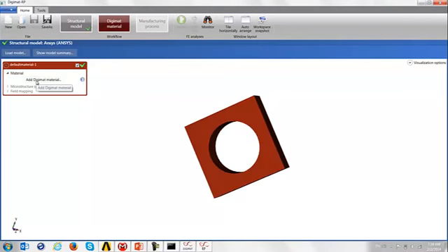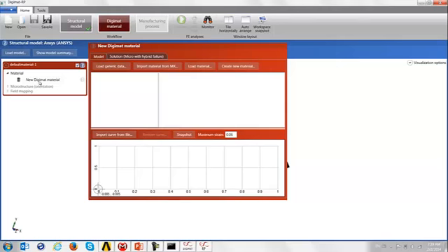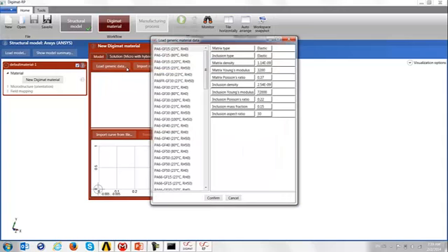And now we would proceed by adding the Digimat material. We have choices of different sources of material that we can load. And in this case, we just take the generic data. So here you see a full list of what we provide for a linear elastic performance. And here I like to choose a PBT glass fiber reinforced with 50% fibers for room temperature. So this is, in terms of material behavior, what is being displayed on the bottom of that window. The solution procedure is micro, so an interactive computation of material properties on the fly during the FE run.